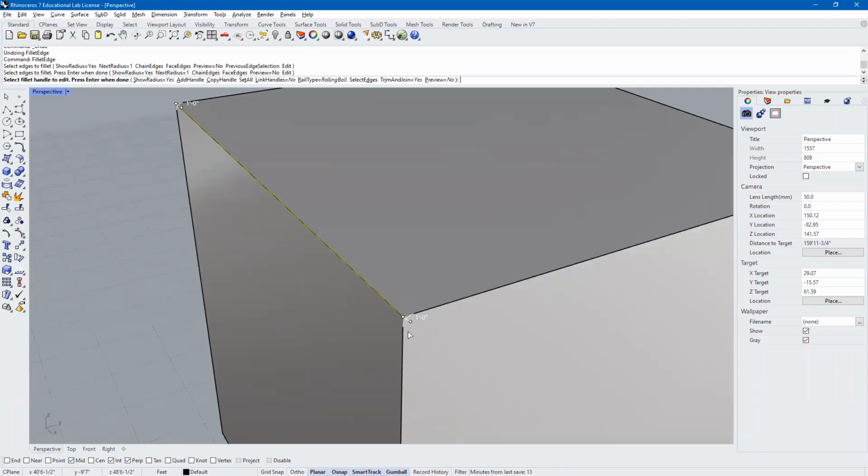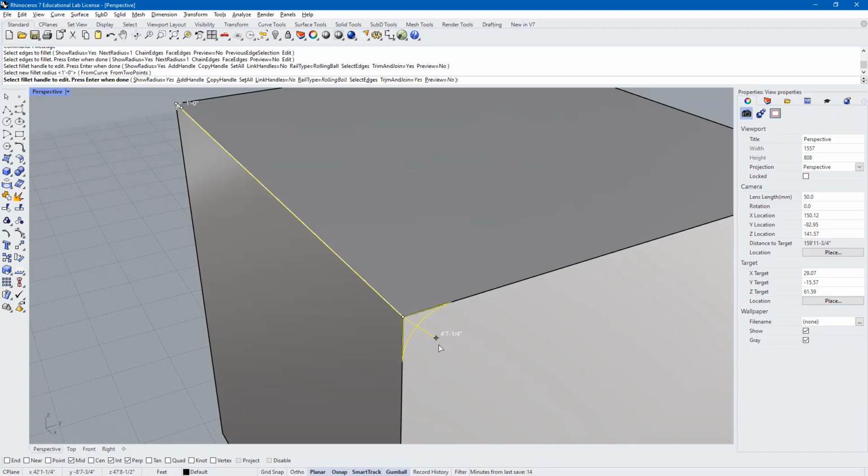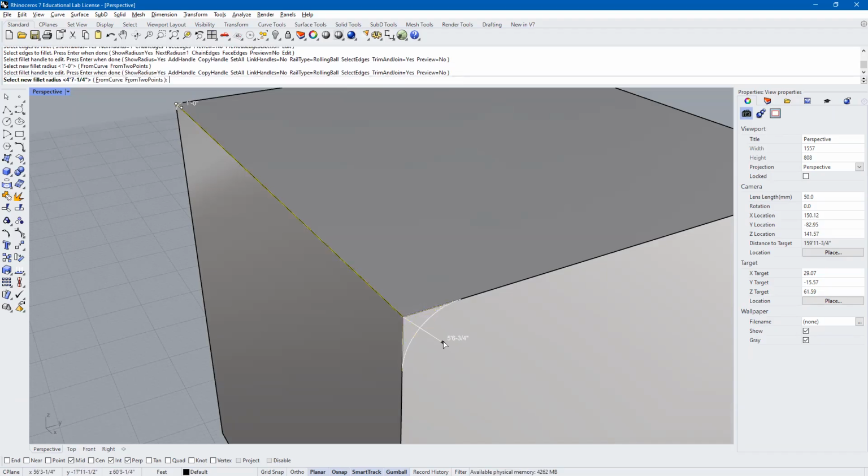I'm going to zoom in and I can click right here on this, I guess, call it the center point of that radius, click on it, and I can start dragging it out and making it bigger. If I want, I could just go ahead and click, and it gives me that distance, rounding it to the nearest 1/4 inch. That's fine. Or I can click on it again, and maybe I want to make it exactly 5 feet. So I type 5 feet on that end, and I lock into it.